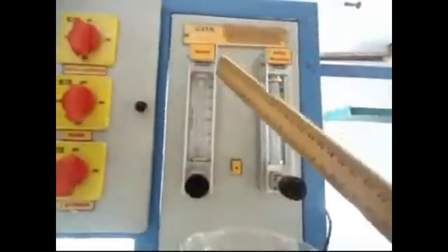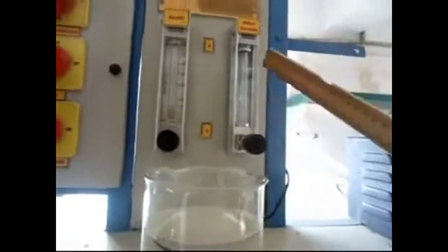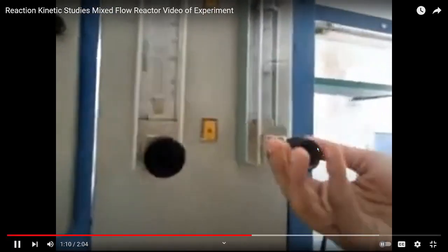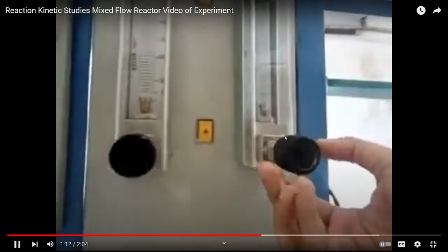We can use the two rotameters to check the required flow rate of ethyl acetate and NaOH. Initially, the ethyl acetate flow rate is set and the required NaOH flow rate is calculated by using the initial concentration ratios required. We set the sodium hydroxide flow rate as well. Set the ethyl acetate flow rate. Start the heating, start the pump, set the flow rate of both ethyl acetate and NaOH.